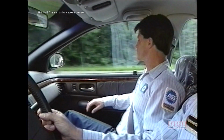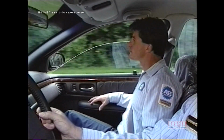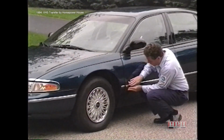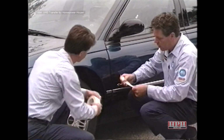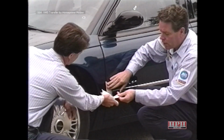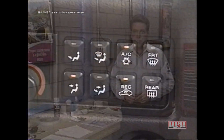If you think the noise may be external, roll down the window and continue to listen. Did the noise go away? If not, it's probably external. Look for any misaligned body components, or try using masking tape to secure loose moldings, drip rails, or any other loose items that may be causing turbulence. You can also use masking tape to bridge gaps or fill voids that may be causing turbulence. If the noise seems to be coming from inside the vehicle, it is probably an air leak.